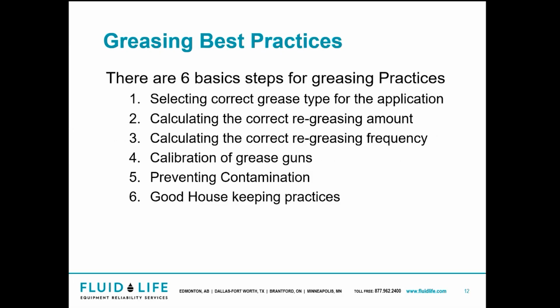So when it comes to greasing, there are 6 basic steps for grease practices. You've got to select the correct grease type for the application, calculate the correct re-greasing amount, calculate how often, the frequency, calibrate grease guns, and prevent contamination with good housekeeping practices.